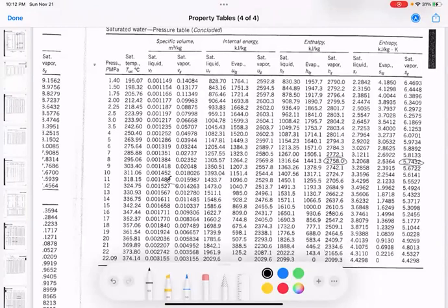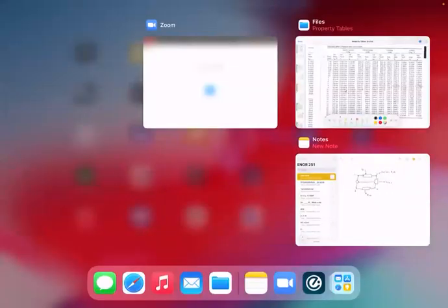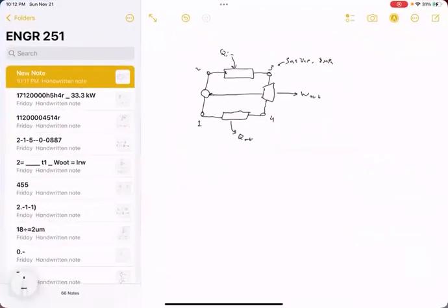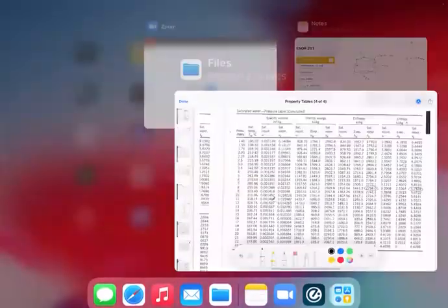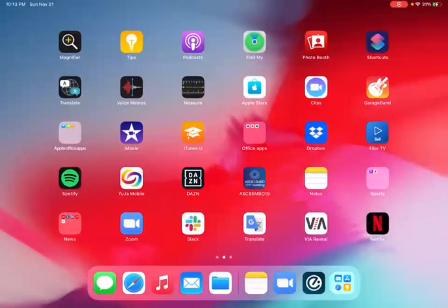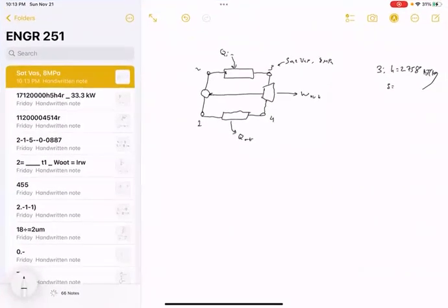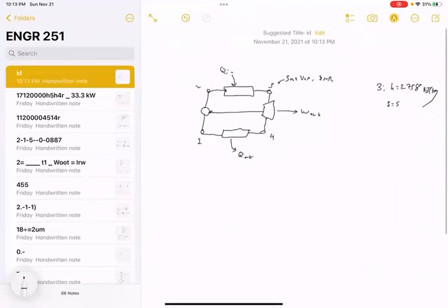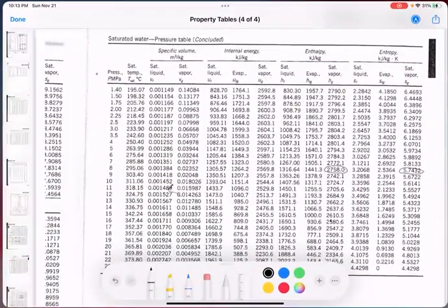So in this case for state 3, 2758 and 5.7, well, let's do it one at a time. 2758 and 5.7432. So at state 3, we have H equals 2758 kilojoules per kilogram. And, oh yes, entropy is equal to 5.7432, and the units are kilojoules per kilogram Kelvin. I just forgot it, 1 second.